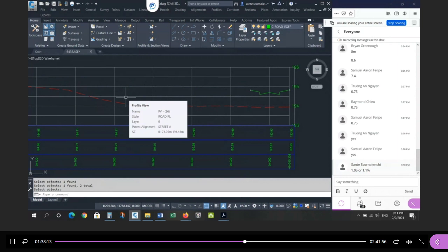But to go around the elbow, the minimum slope can't be 0.5%, which is the recommended minimum. It has to be steeper to satisfy the gutter grade. Okay? Do you remember this discussion from last year in CDA? I hope.